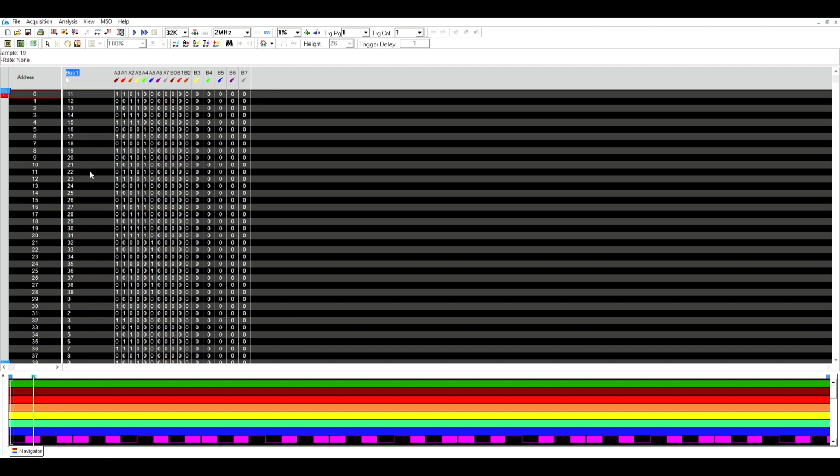It's counting 1, and then 39, and it goes back to 0. The fallback address is 0, and it's parallel loaded into the counter, so it goes back to 0, and then it will count to 39 again over here, and then it goes back to 0 for the second time. So it should get to 39 16 times. This is the second. We can count whether this will be the case. This is the third. No, this is still the second. Let me count this from the beginning to make sure that this is working okay.